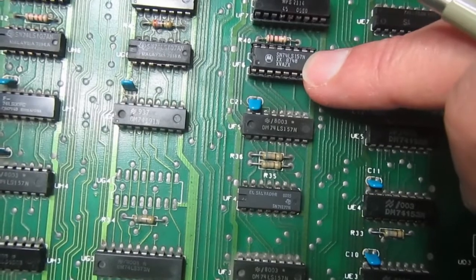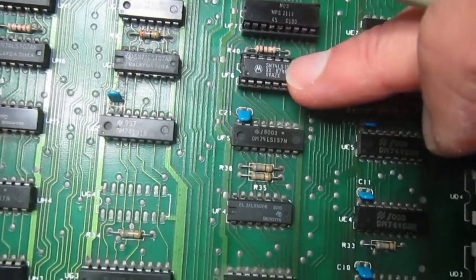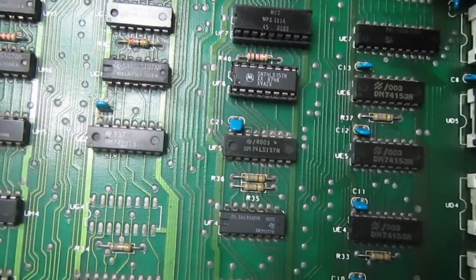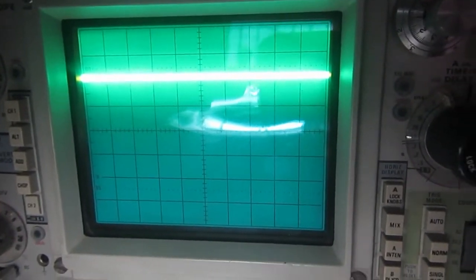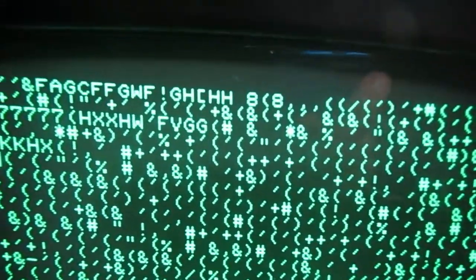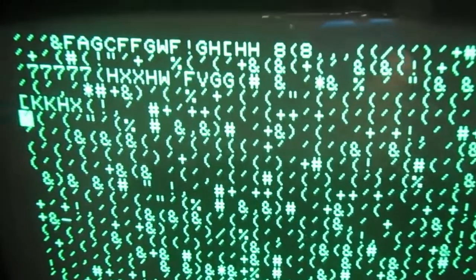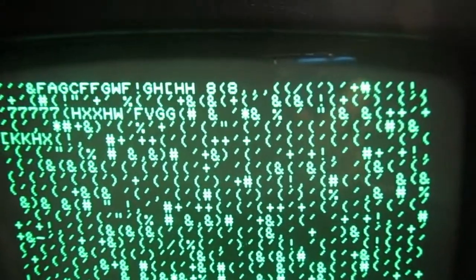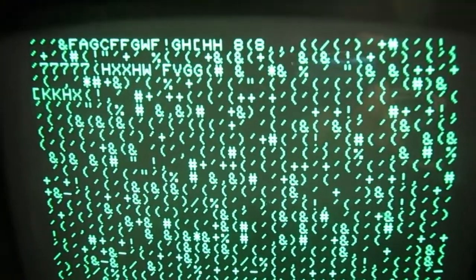the old 157 should have been bad, and indeed with this new 157 here, the signal on pin 19 looks nice and clean. And without the 244 we have a flashing cursor, no moving characters. Of course characters are wrong because there is no bus driver on the lower nibble. So I guess we are on the right track. So let me install a new 244.